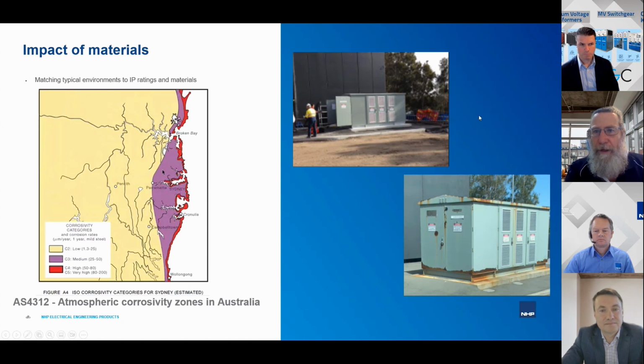And I guess being in the industry in New Zealand, most of my career I've been exposed to things like geothermal, hydrogen sulfide, very harsh coastal environments. And so for me, knowing that this kiosk was being installed so close to a surf beach, quite clearly it should have never been manufactured out of just mild steel with powder coating.